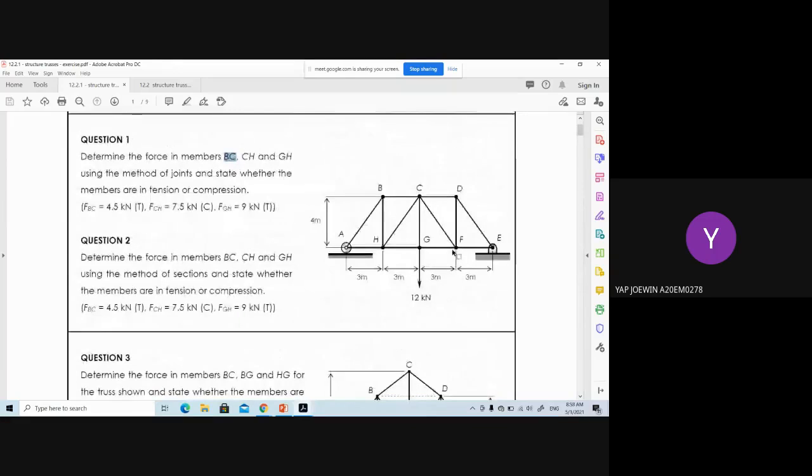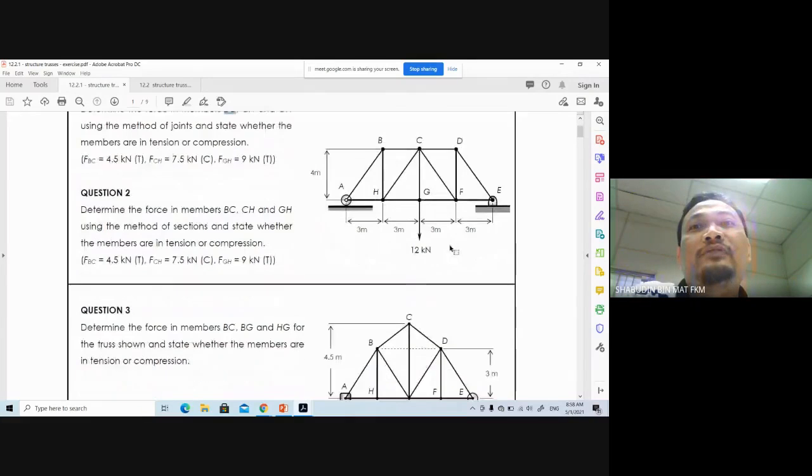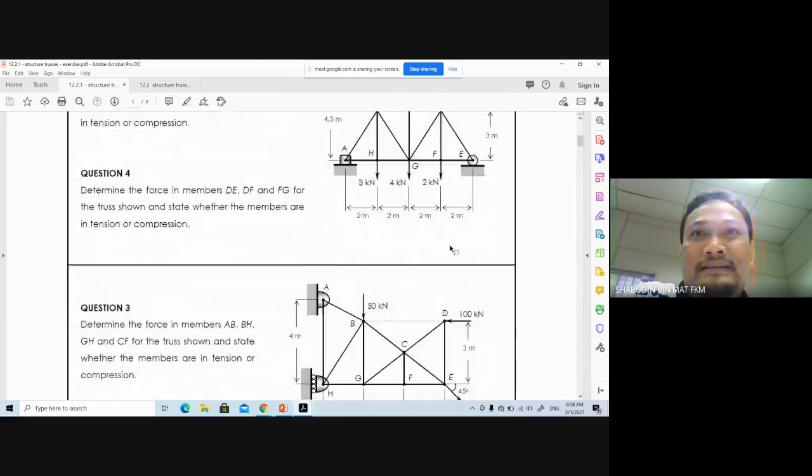Sir, when we're doing the section method and we found that in the trusses there are some zero members, we can just ignore it? We need not draw it in the free body diagram, right? Better draw it, say force HG, then put it equal to 0. Say FBC, if it's 0, you draw it also. FBC is equal to 0. Better to safeguard your mark.